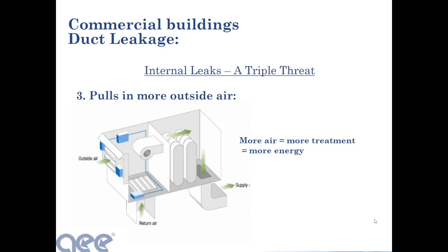Think about it like this. If you pop your ceiling tile, do you need fresh air in your ceiling vents? Do you need fresh air in your vents? Well, if you have air duct leakage, that's what you're doing. You're paying for your air conditioner system to condition air, and you're running it through interstitial spaces. It's a waste of money.